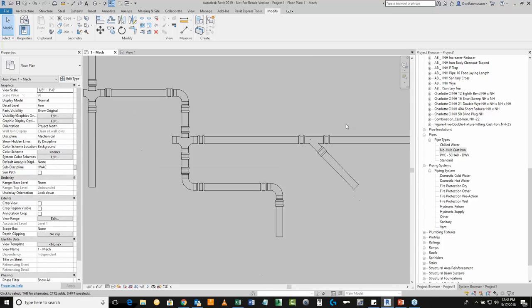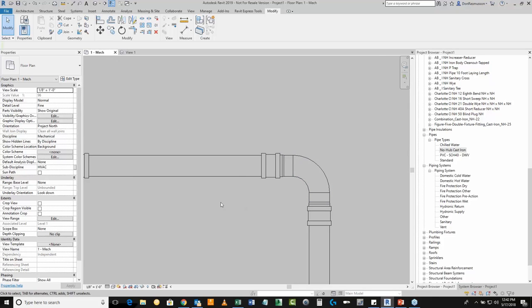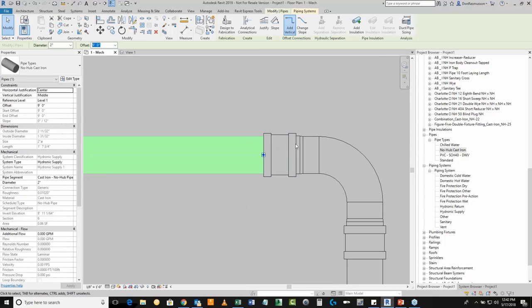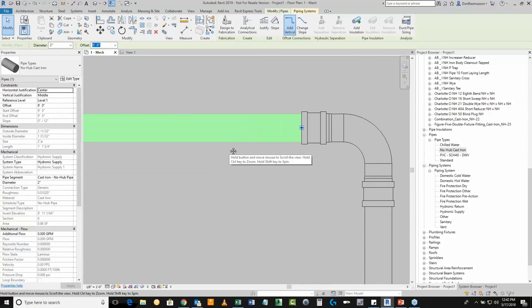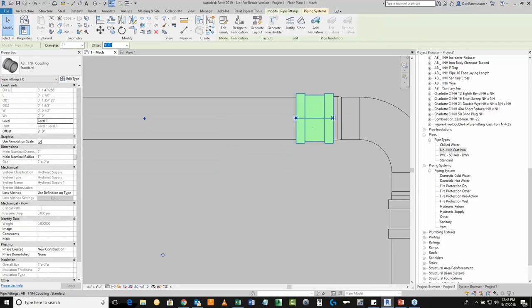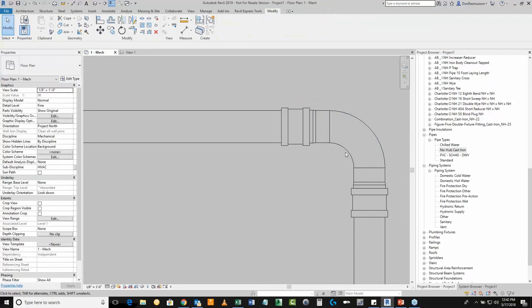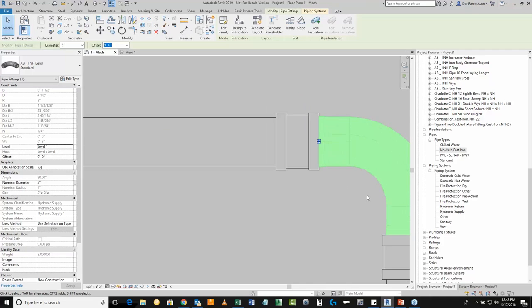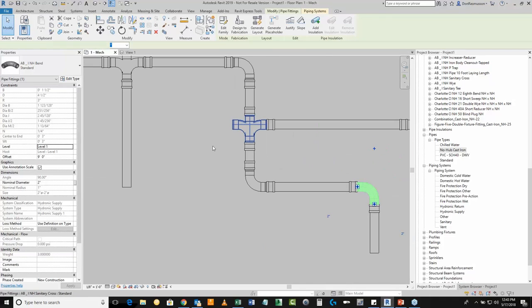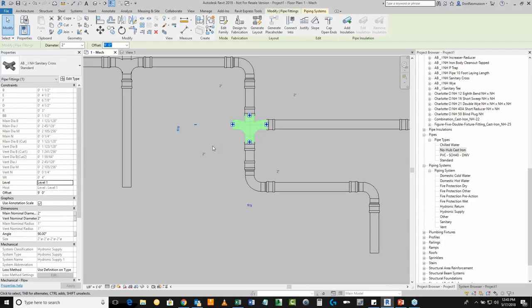As you look around some of these fittings here, guys, we can see some obvious challenges, right? The connectors are in the wrong spot in this coupling, so I wouldn't be able to do an accurate pipe length schedule, but that's simply modifying this coupling family and moving some connectors around. I see the same challenge maybe here on the elbows, and obviously some of these other fittings too. I will want to inspect to make sure that the connectors are in the right spot, verify that even though it came from a manufacturer that it is dimensionally accurate. I've seen things like that happen in the past too.